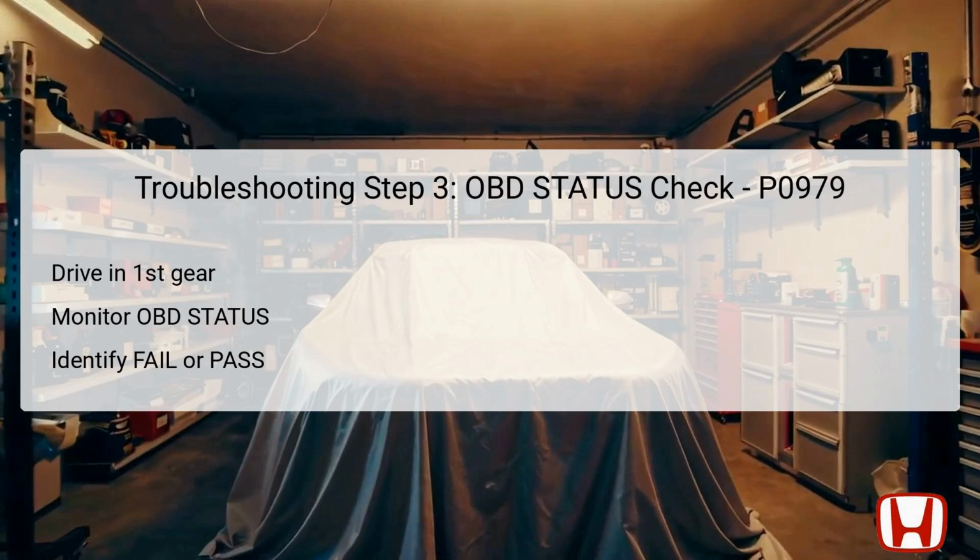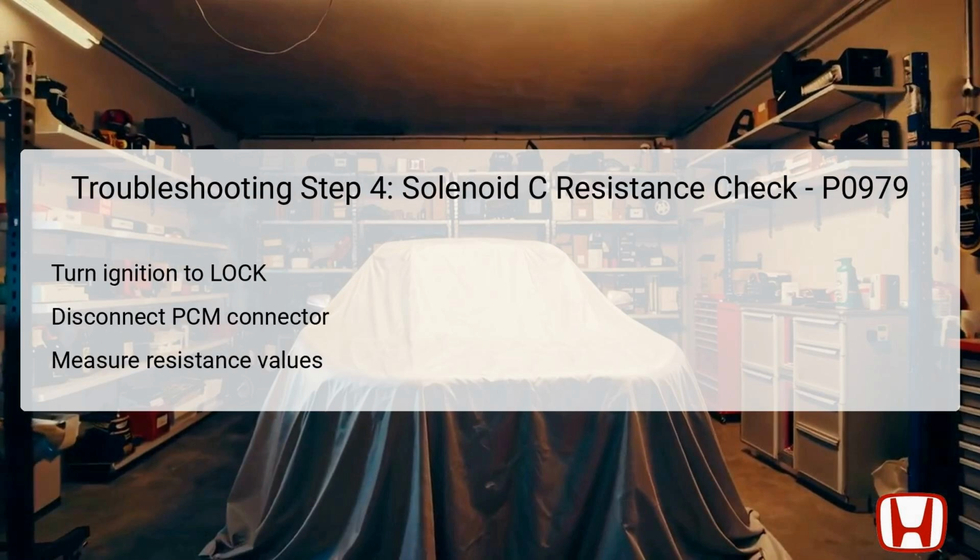Should the HDS show not completed, a repeat test drive might be necessary to achieve accurate results. In step 4, you will be performing an internal resistance check on shift solenoid valve C. Begin this process by turning the ignition switch to the lock position, ensuring all systems are powered down. Next, use the HDS to jump the SCS service check line, initiating the necessary diagnostic preparations.